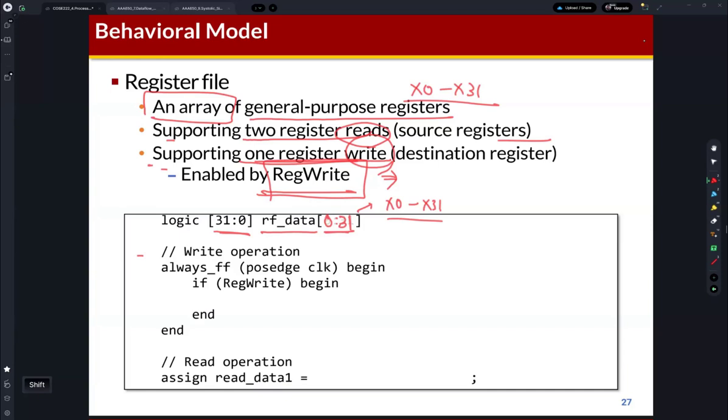It is because it includes the write operation. And this write operation is performed just before the rising edge of the next clock. So it should be synchronized. Otherwise, we will get an incorrect result for some specific cases.